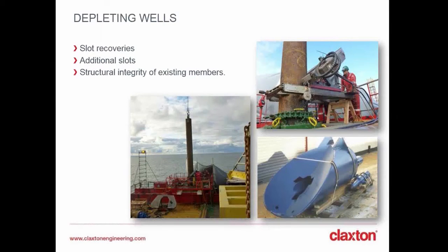On depleting wells, after production rates start decreasing and finally reach a level at which they are not economically viable, the well might require to be abandoned. If the platform is still in good condition and structurally sound, it might be decided to recover the old well and perhaps run a new well making use of the existing guides. This can be done using a whipstock that's shown in the picture in the bottom right.